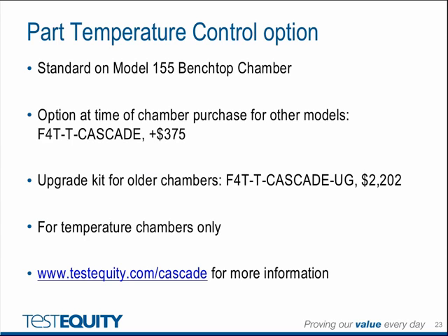Cascade Control is only available for temperature chambers. It is not appropriate for humidity chambers because humidity and air temperature are inextricably linked. You cannot have stable humidity control if the air temperature is not fixed.